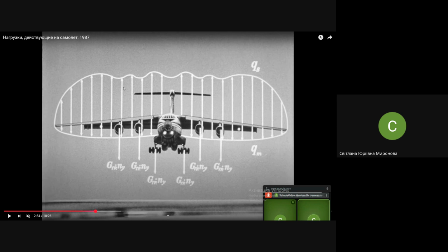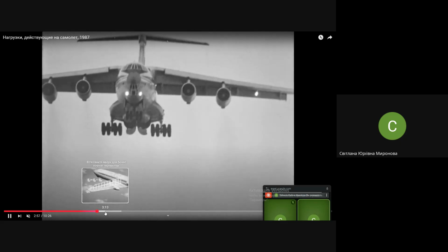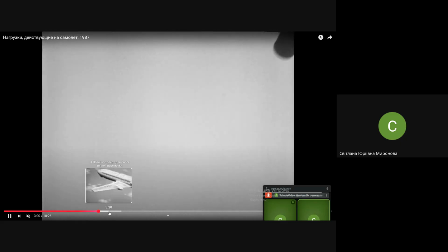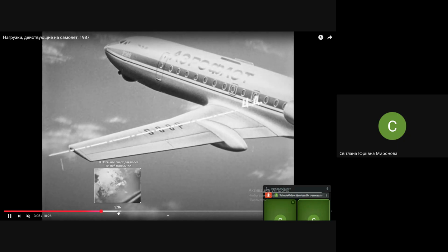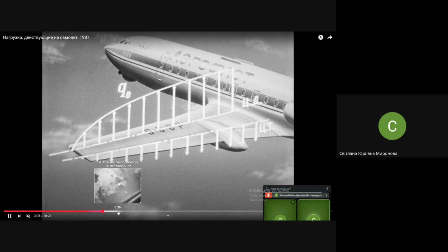So pay attention to the resulting diagram of loads. Instead of increasing in this place, it has reductions in some places. This reduction is in the place where we have engines and in the place where we have the fuselage, because it's also like relieving the wing altogether. In this place, retracting the landing gear, and what next are you going to show us, again about loadings.